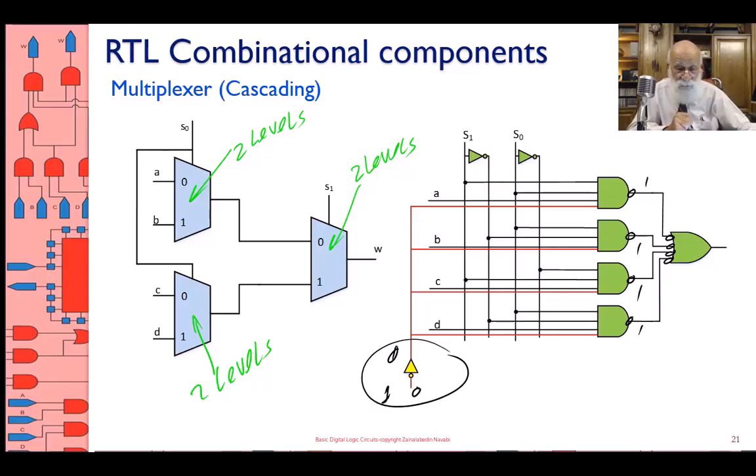And therefore the NANDing of all these ones gives you 0. That means if it is disabled, the output is 0 regardless of what A, B, C, D input values are. It only works if my enable is active. Active low means 0. If it is a 1, the output remains 0. All right, so this is a multiplexer with an enable input.